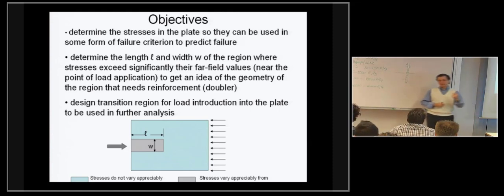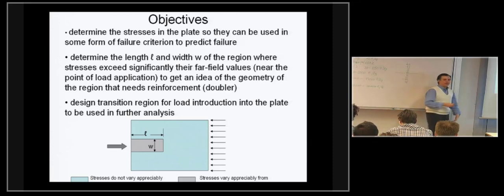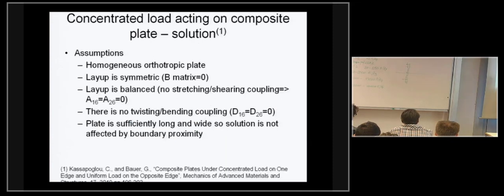because after all, ultimately we're interested in a design that would work, and one of the questions we would have to ask ourselves is, okay, how big of a doubler, how big of a reinforcement do I need in terms of a length and width? In order to do that, we need to determine the stresses for this problem, and we make some assumptions.